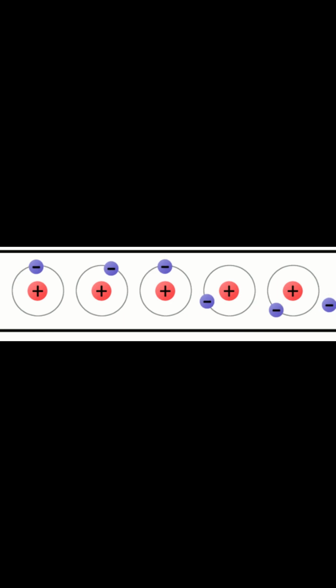In normal operation, current flows through the hot and neutral conductors only. The grounding conductor is used to help prevent a shock hazard in the event that the ungrounded or hot conductor comes in contact with the case or frame of the appliance.